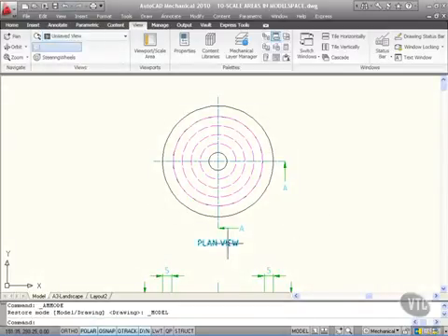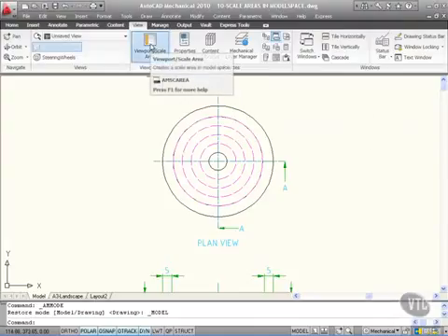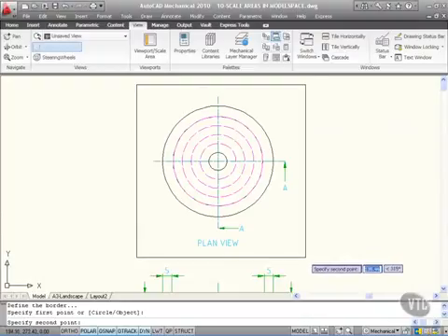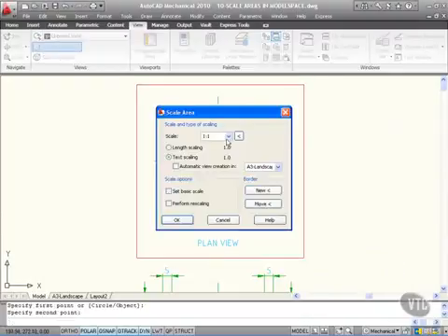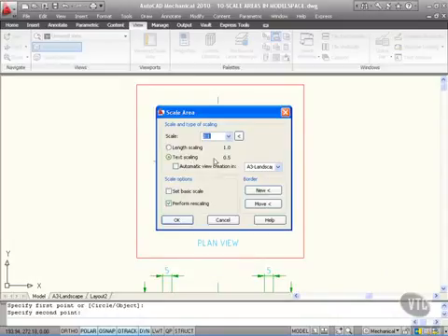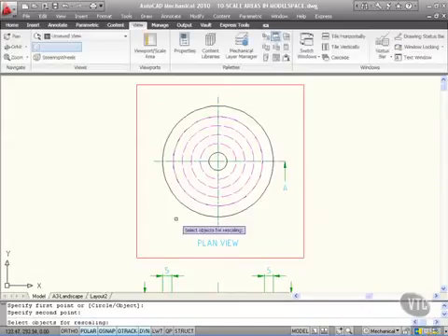The only objects that need scaling are the annotation. The object itself, we've told it what scale, haven't we, in the scale area dialog box. So if I go back to scale area here, click here like so, set the scale area. The scale is going to be 2 to 1. Text scaling will become half size. As you can see, 2 to 1, 0.5. That all cancels each other out, so the text is 1 to 1. Automatic view creation in A3 landscape tab, like we did before.